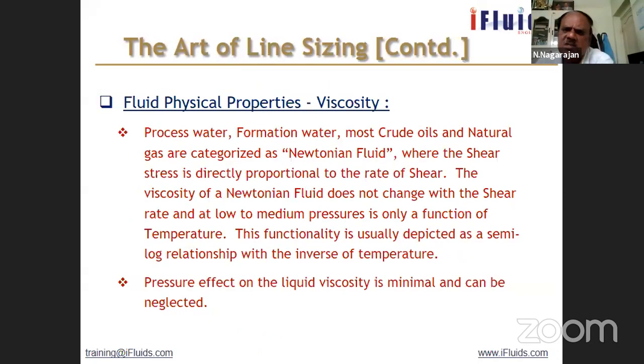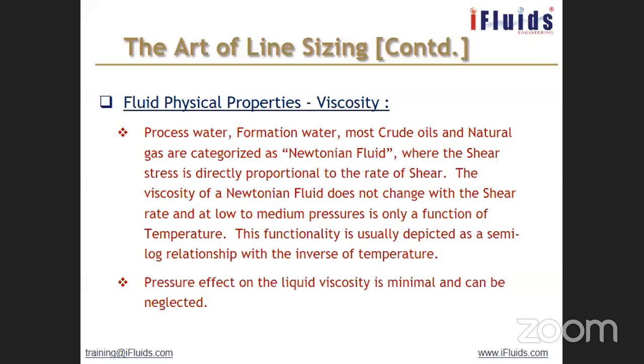Process water, formation water, most crude oils and natural gas are categorized as Newtonian fluid, where the shear stress is directly proportional to the rate of shear. Maybe you may have to refresh slightly your fluid flow, fluid dynamics chapters. The viscosity of a Newtonian fluid does not change with the shear rate, and at low to medium pressures is only a function of temperature.